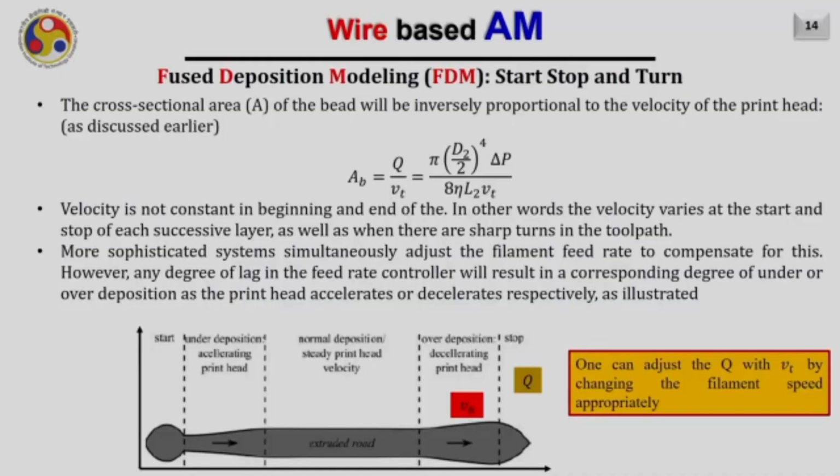If this heat transfer coefficient is low, then of course for a longer period of time the deposited bead will remain at a particular high temperature, which will help the bead to form the bond with the neighbor beads, and therefore the overall strength of the part will increase.